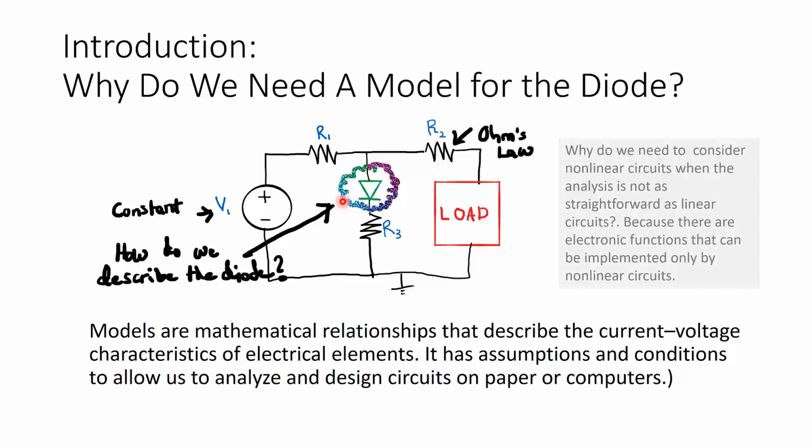And again, as I was saying just now, a diode is a non-linear circuit element. A resistor is a linear circuit element because it obeys V equals IR. That is a linear relationship. But a diode obeys Shockley's equation from our previous video, and it is non-linear, meaning that you'll have to deal with exponential expressions in the mathematical equation.